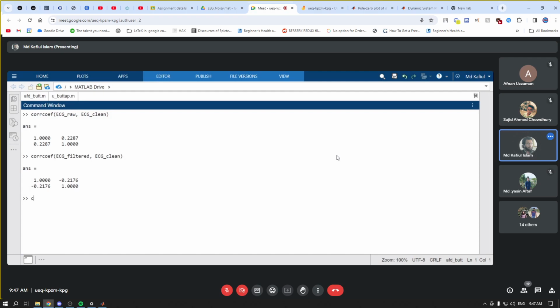What else? We have talked about the 4 performance parameters, right? So this is how you have to approach the project. You see that we tried the IIR filter first. The IIR filter frequency response looks good, but when we applied the filter to the application, there was a huge problem. Then we tried the FIR filter. We found that there is some lag with the FIR filter, and it is not exactly as expected. The signal has certainly improved, but it is not good enough to be usable for ECG signal characteristics analysis.